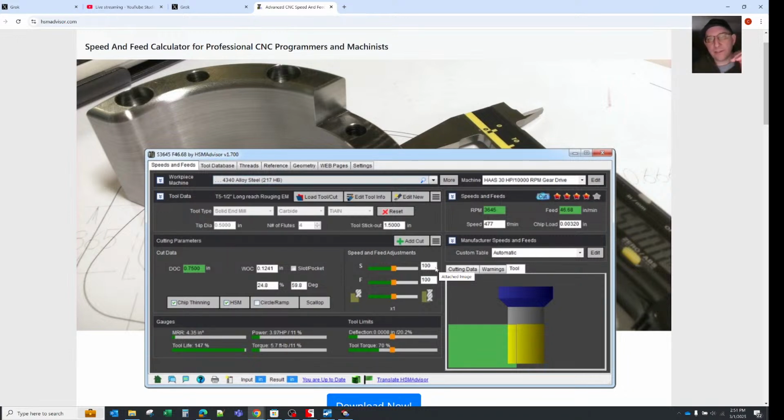So by utilizing this function of the high-speed machining, or the HSM Advisor, the cutting force itself, you could really tune in your workholding. You give yourself a safety factor, right? If you've put all of your input in and you're looking at your heaviest roughing and the cut says it's only going to take 150 pounds of cutting force, well, then you could tune in the clamping force, so maybe you have 200, 300 pounds. Most people will throw something in a Kurt 6-inch vise and never think about how much clamping force they're actually putting onto the part. They're just concerned about how it's going to spring when they release it. So this allows you to really dial that in.